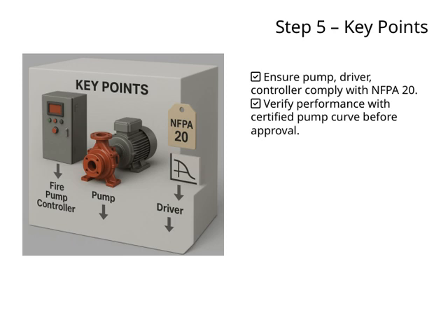By following these points, we make sure that the fire protection system is both safe and effective, aligning with the overall theme of reliability and code compliance. So remember, checking for NFPA 20 compliance and verifying performance with certified data are key to a successful installation.